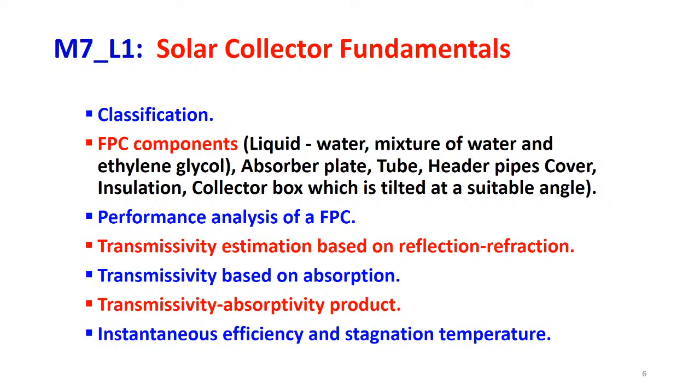And finally, we have studied the definition of instantaneous efficiency, how it can be evaluated for a flat plate collector, and one very important parameter called stagnation temperature. We have studied the importance of stagnation temperature and how it can be useful for the design of a flat plate collector.